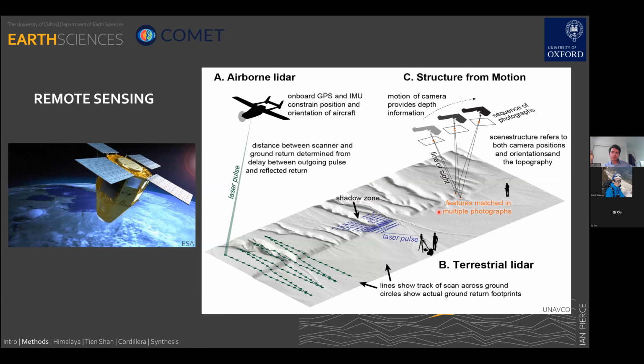Mapping and measuring faults requires high-resolution imagery and topographic data. I use satellite imagery and aerial imagery, LiDAR, and structure from motion models to produce this topographic data. LiDAR uses pulses taken from an airplane or a terrestrial scanner to measure distances and reconstruct topography. More recently, I've been developing applications for mobile LiDAR scanning using the scanners built into the newest iPhones and iPads.